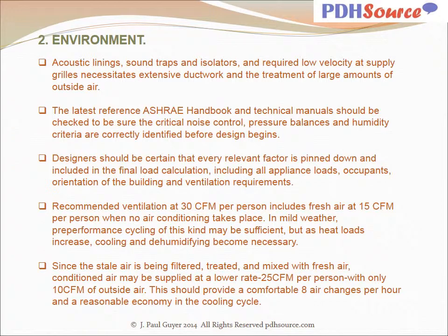Acoustic linings, sound traps, and isolators, and required low velocity at supply grills, necessitate extensive ductwork and the treatment of large amounts of outside air. The latest reference ASHRAE handbook and technical manuals should be checked to be sure the critical noise control, pressure balances, and humidity criteria are correctly identified before design begins.